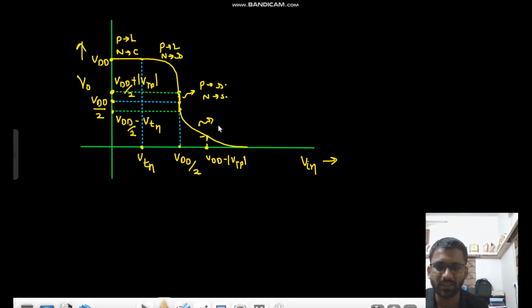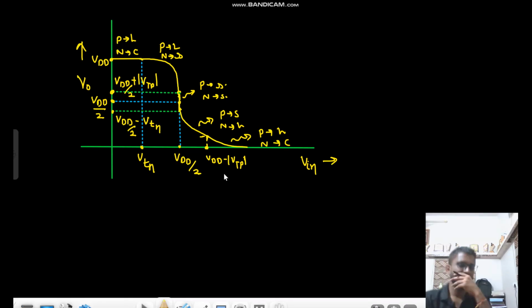So in this region your PMOS was in saturation and your NMOS was in linear region, and in this region your PMOS was in linear region and your NMOS was in cutoff region. Okay, I hope you have understood the concepts now, right?